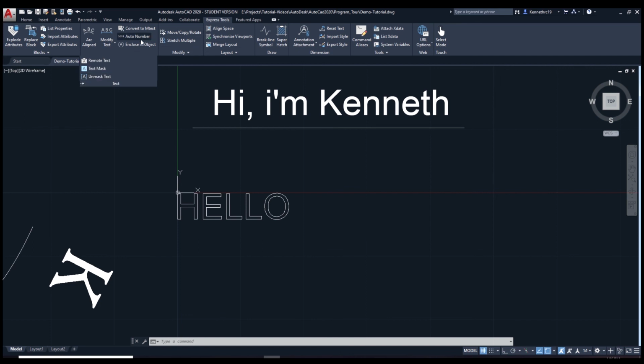Okay. Here's convert to mtext. So the command we entered earlier to turn it into mtext, that's the same command. Here's auto number. Adds sequential numbering to text objects. Enclose in object surrounds text or multiple text with circles, slots or rectangles.